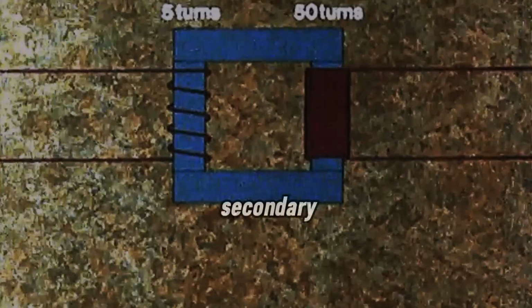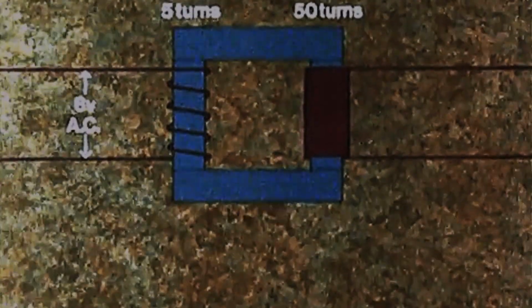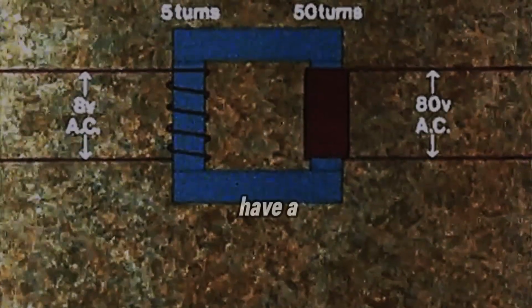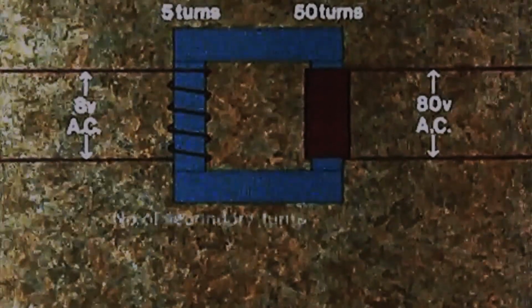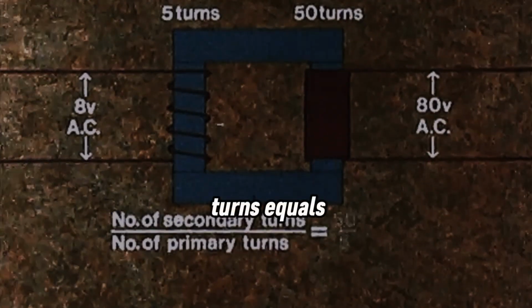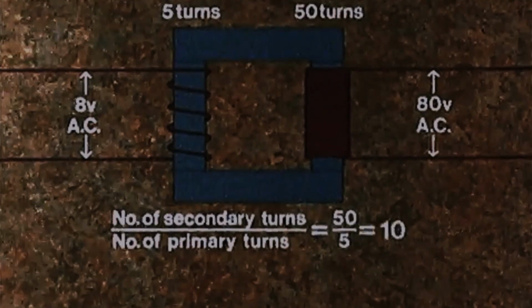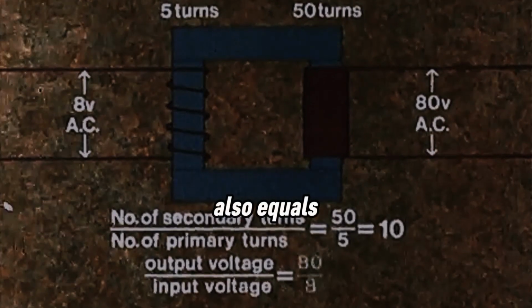Suppose we have 5 turns of wire in the primary coil and 10 times that, 50 turns, in the secondary. And suppose we apply an input EMF of, say, 8 volts AC. The output EMF will be 10 times that, 80 volts AC. And we will have stepped up the voltage and we have a simple transformer. Let's look at it more carefully. The number of secondary turns divided by the number of primary turns equals 50 over 5 equals 10. But the output voltage divided by the input voltage also equals 10.